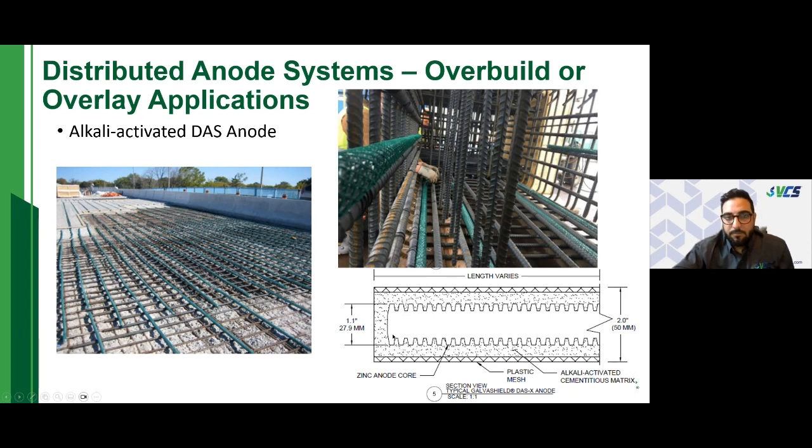On the left, this was an overlay application where the deteriorated sections of the bridge deck were removed, and the DAS anodes were laid at the design spacing to provide cathodic protection. And the image on the right is a new construction.